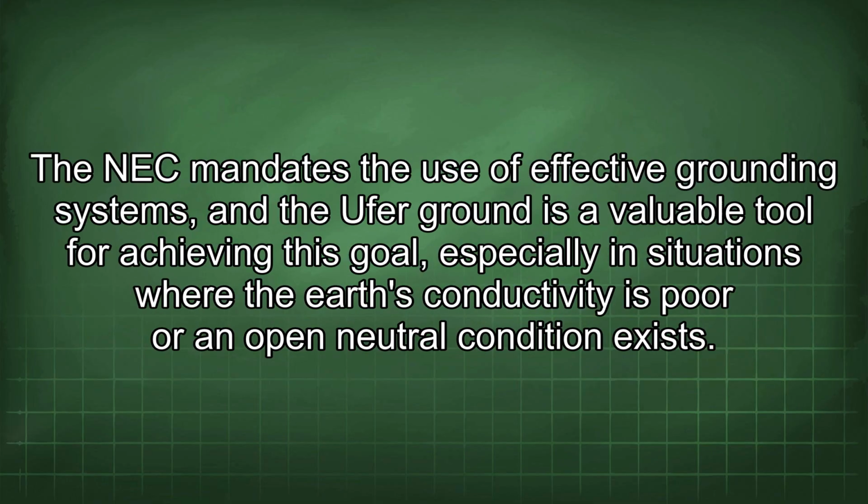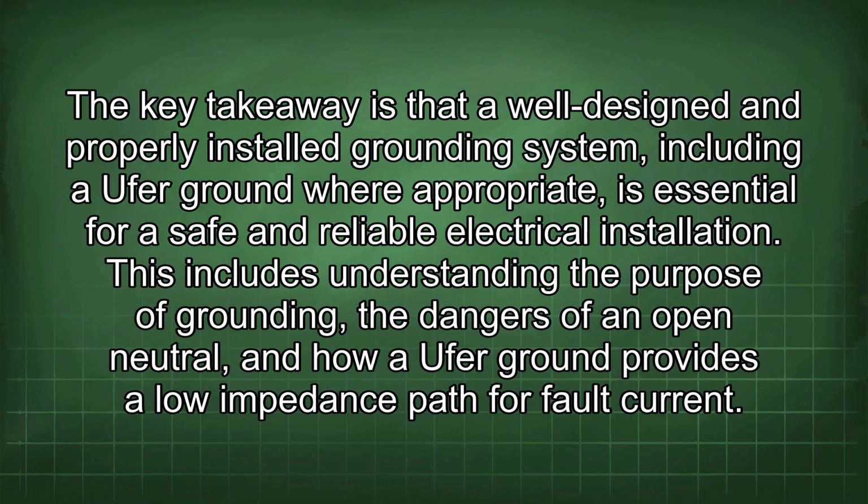The NEC mandates the use of effective grounding systems, and the Ufer ground is a valuable tool for achieving this goal, especially in situations where the earth's conductivity is poor or an open neutral condition exists. The key takeaway is that a well-designed and properly installed grounding system, including a Ufer ground where appropriate, is essential for a safe and reliable electrical installation.